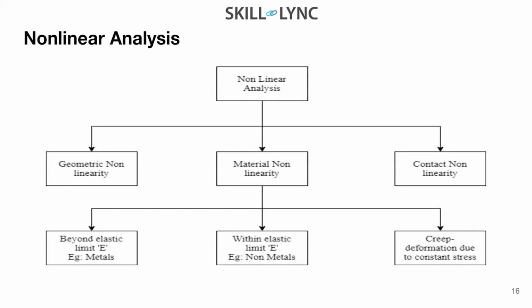Then there is contact nonlinearity, which depends upon your contacts and what is happening at them. Within material nonlinearity, we have seen that beyond elastic limits, your metals become plastic. For non-metals, within the elastic limit only it is plastic. And if you have a constant load, creeps are developed. So these three are the types of your non-linearities.